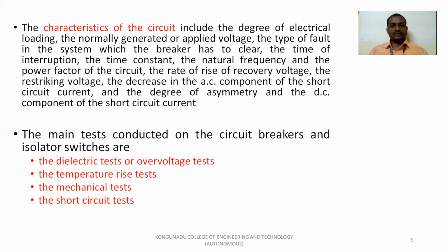The major tests conducted on circuit breakers and isolator switches are, first, the dielectric test or over voltage test. Second is the temperature rise test. Third is the mechanical test. Fourth is the short circuit test. These are the very important tests to be carried out on the circuit breaker and the isolators.